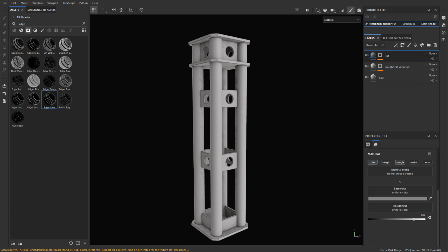Now we have 3 other meshes. One that's a stand and then 2 meshes inside one, so we can texture them in Painter and see the results at the same time for the 2 different straight and arch beams. So how do we bring those in and reuse the same effects that we used for this mesh on the other meshes, without having to set up exactly the same thing, having to write each of these down, then apply it to the second mesh and the rest of the meshes as we bring them in? So what you could do is reuse the same scene and just replace the mesh with a new mesh.